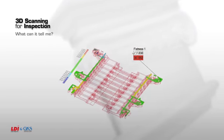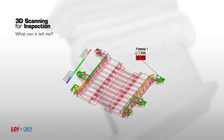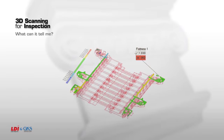One advantage of 3D scanning for inspection is to show geometric dimensioning and tolerancing. In this case, only the surfaces involved in the flatness callout of 30 thousandths are shown. All the areas in green are within tolerance, and the area in the upper part of the image is out of tolerance by 32 thousandths, so you can quickly see where your deviation might occur.